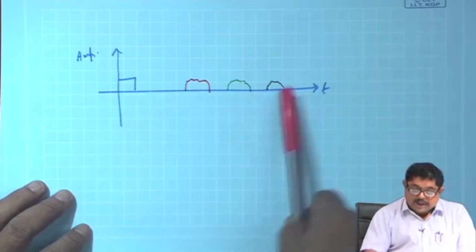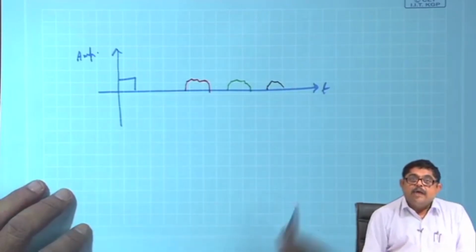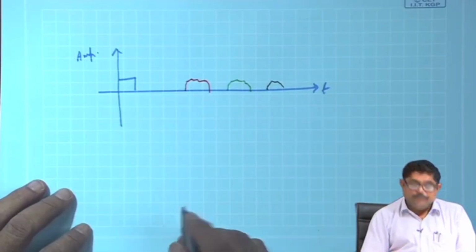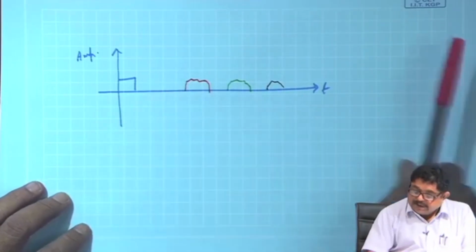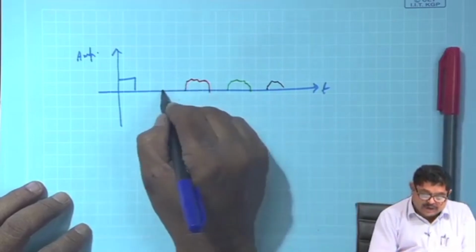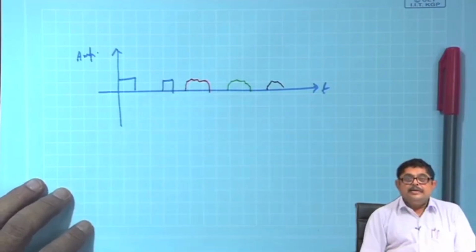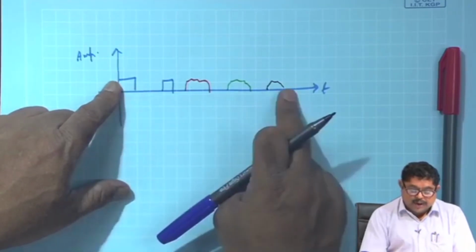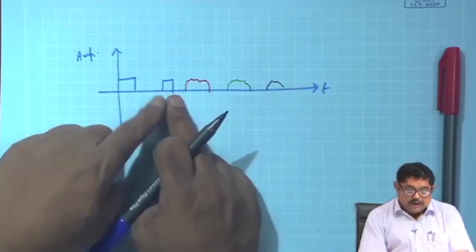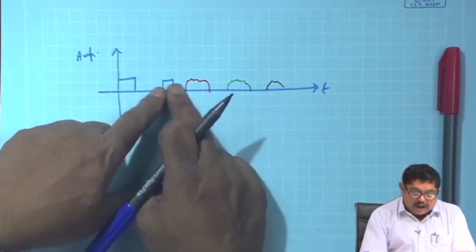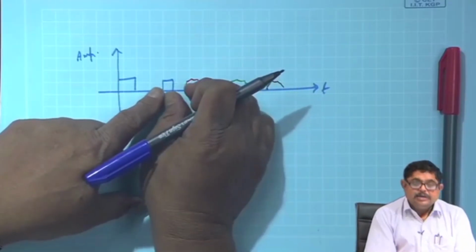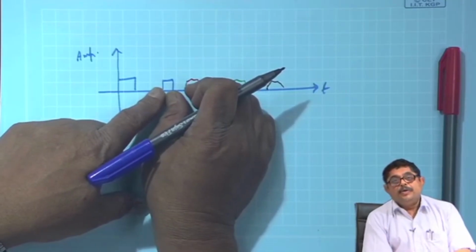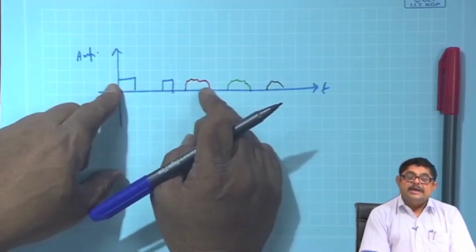Now, the question is, integration means I will have to go on sending. So that means I will have to send another signal. If I send the next transmitted signal here, then though these echoes have come in response to the first one, I will think that this has come after this return. So this range, if I calculate, will be very small, whereas in reality it is much larger.